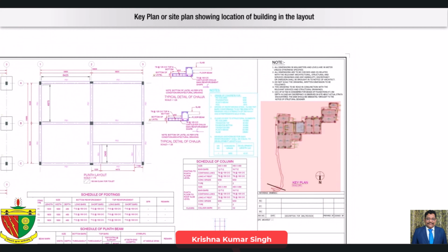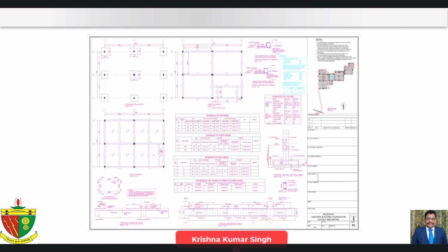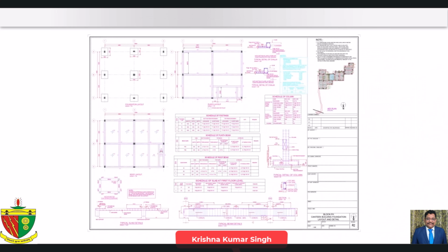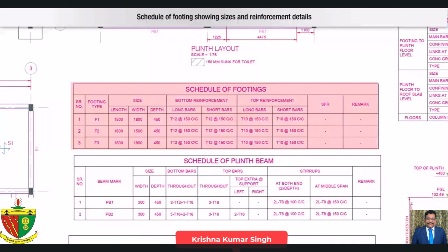Key plan or site plan showing location of building in the layout. Foundation and column layout showing grid lines distances. Schedule of footing showing sizes and reinforcements details.